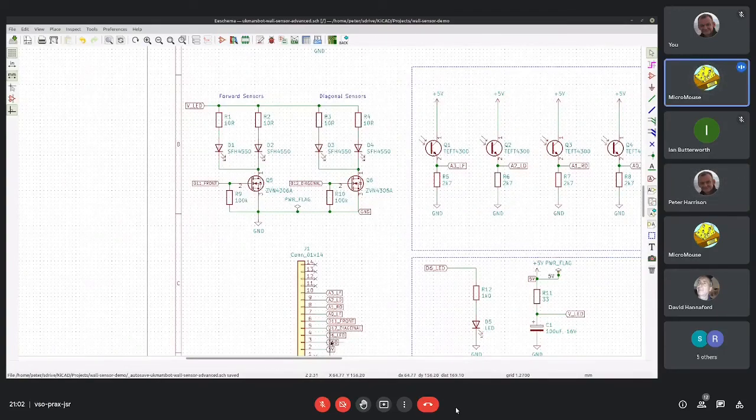So it's saying that ground symbol in Eagle, that would constitute a label called ground. Yes, but in this, it just doesn't. No, it's an annotation, right? It's an annotation which also gives a name to a net where that's appropriate, I believe. I haven't looked into the details, but if I took away those two labels, nothing would change. Right, and you could put a ground symbol on the connector at the bottom, and it would then connect. Yeah, it would be fine. We can try it later.